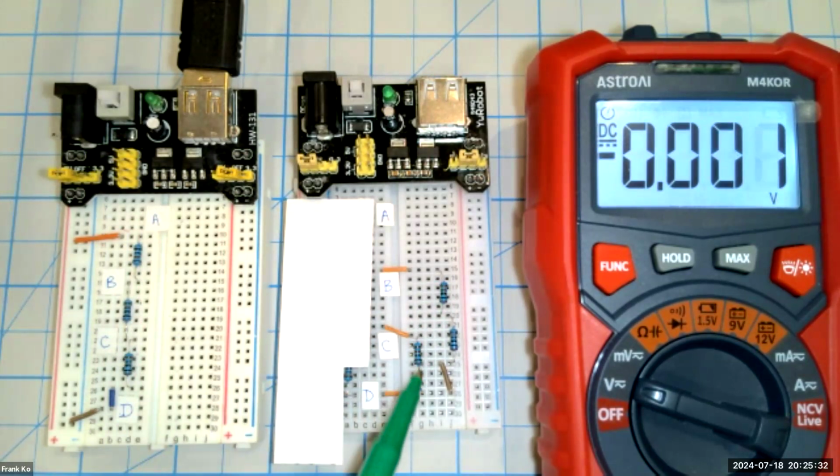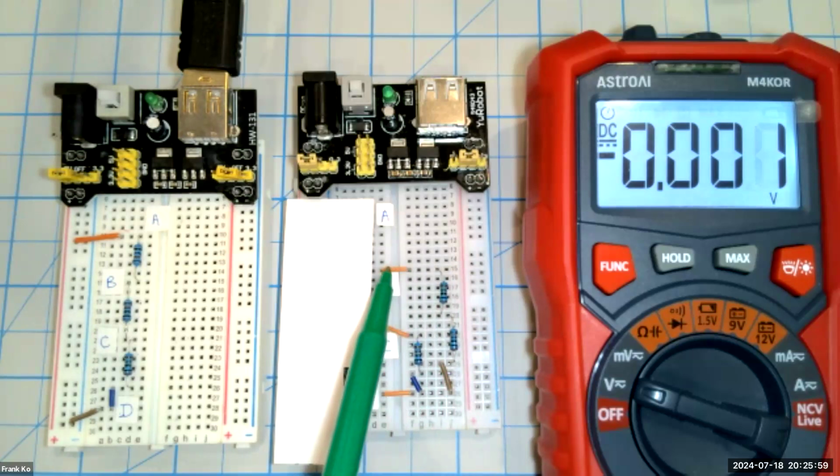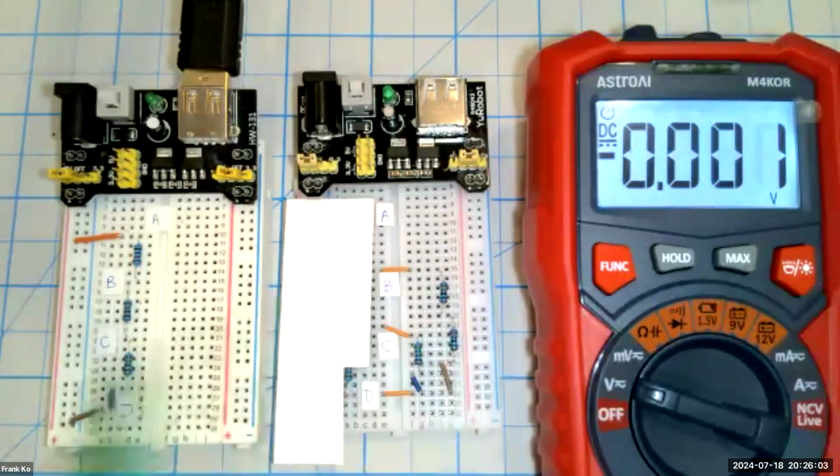So R4 is here. R4 is the 2 kilo ohm. It will have 1 milliamp flowing through it, and it will be attached to point B. I have these two resistors in series with each other. So this is 2K, this is 2K. So the combination for R5 will be 2K plus 2K, giving me the 4K that I needed for R5. And that is attached to point B in order for us to be able to enjoy 4 volts at point B.